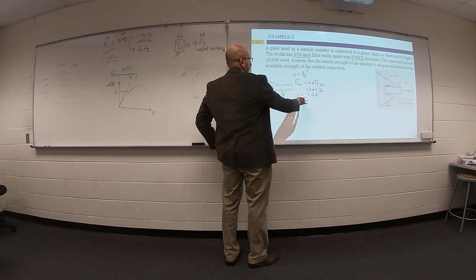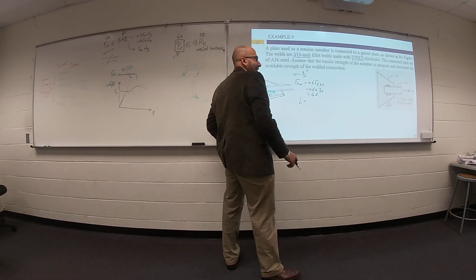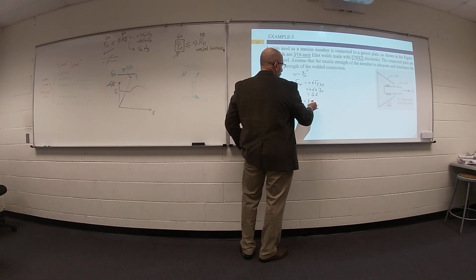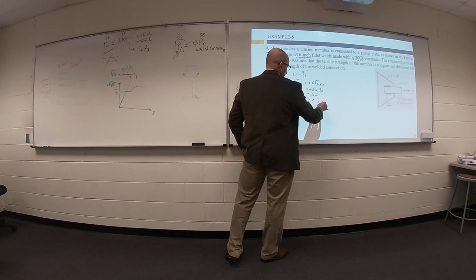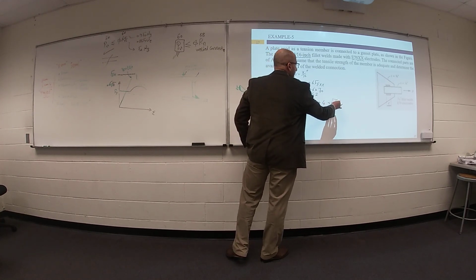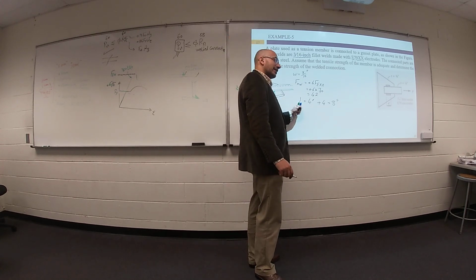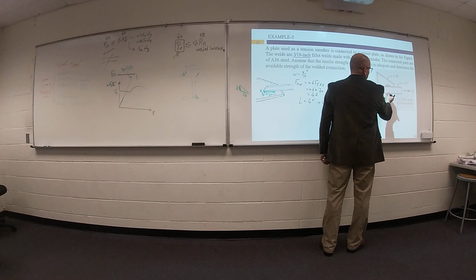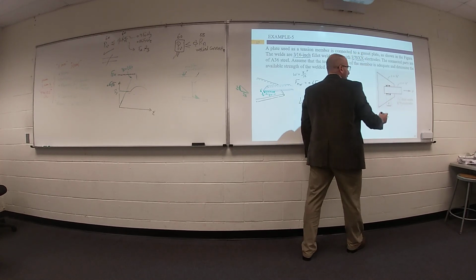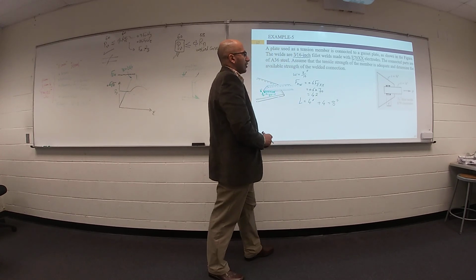Also, from your connection, your length of weld equals 4 inch. Actually, we have another 4. So your L equals 8 inch. What is the total length of your weld? Actually, we have 4 inch from this side and another 4 inch from the other side. So your total length of weld equals 8 inch.